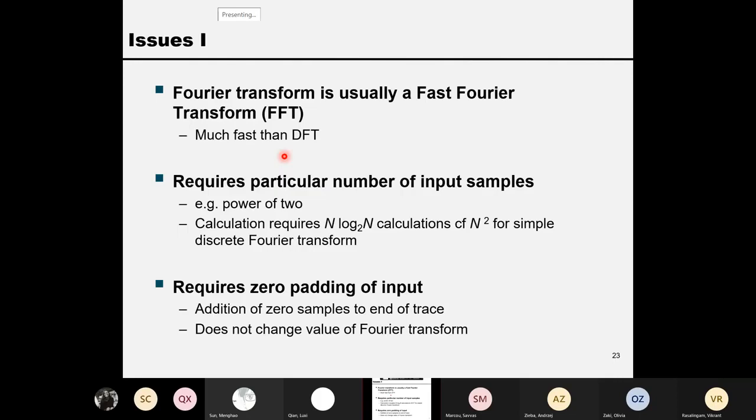For the new time series of length n/2, you fold again, and you end up with n/4, right? And so on and so forth, until you end up with 8 samples, fold again 4 samples, fold again 2 samples. Of course, 2 samples cannot be folded further, right? So at the end, you only need to calculate the 2-sample Fourier transform, okay?